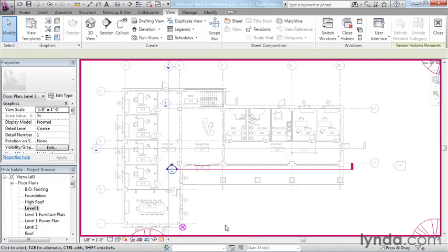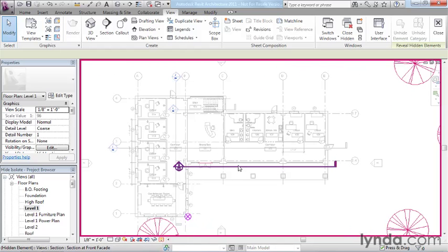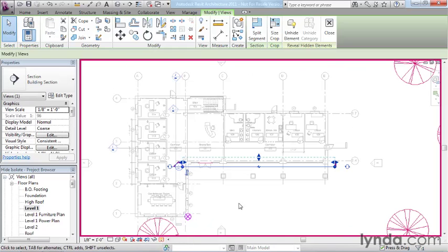And instead of the cyan colored border that we saw before, I'll get this sort of maroon colored border going around the screen, and it will indicate to us that we're in reveal mode. It grays out the model, and then anything that's hidden in view will display also in this sort of reddish maroon color. And you can see, if I zoom out just a touch, that the site plan was already hidden in this view when we started. And when I zoom back in, this section that we just hid a moment ago ourselves is hidden. And I can select it.